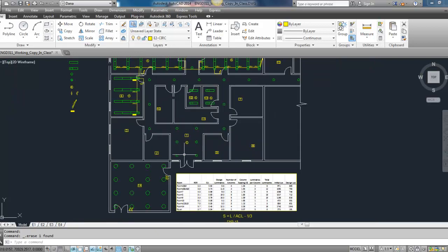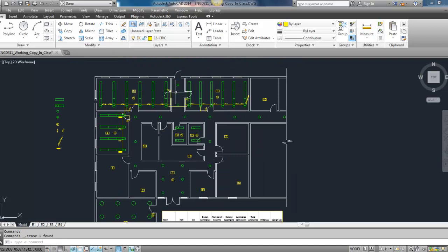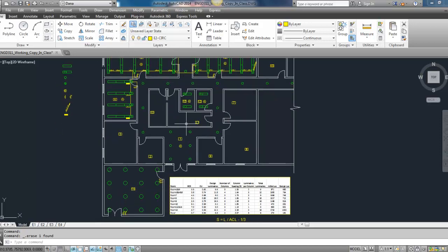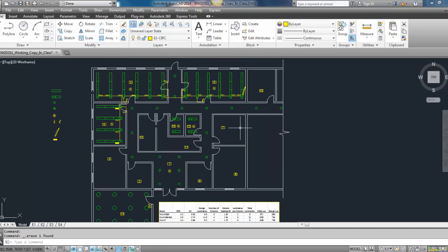So you're going to label each of these luminaires as well with the circuits that they're on. We have 19, so actually we probably could get away with one circuit for all of these. I know 19 is more than our maximum of 18, but again, that's just a guideline. It's not a set in stone rule, and it doesn't make sense to have one of those luminaires on a separate circuit than all the rest. Just makes sense.